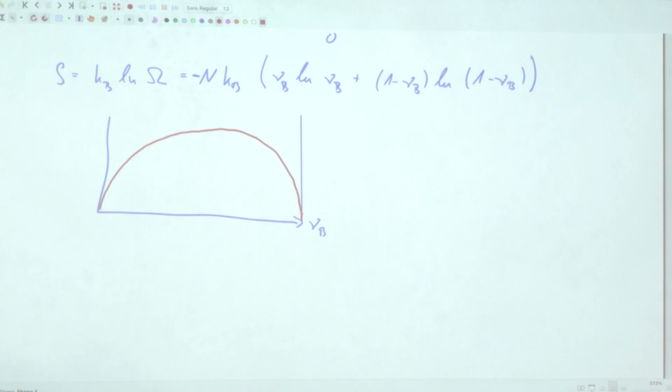I don't know whether you ever had to do with pure aluminum, pure copper, or whatever. You can pay an enormous price for 3959 or so of these. So this 59 means 99.999% purity plus some extra. Typically the commercial aluminum is 99.5, so it contains 0.5% of iron mostly and some other elements. So if you need for experiments 3, 4, 5, 9 aluminum, it's exponentially increasing in expense. And this is because the entropy here is so steep.